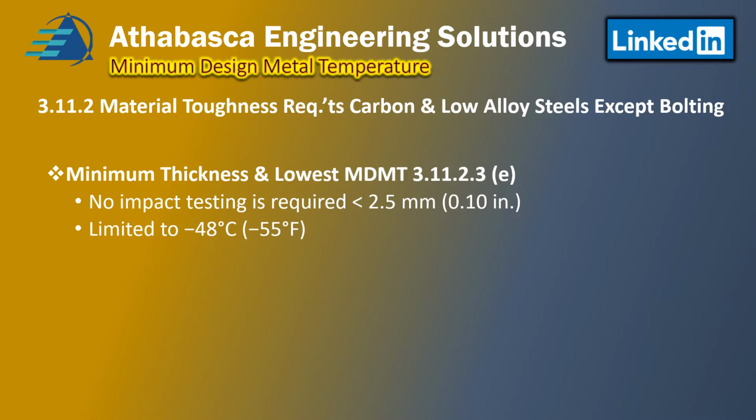The second one is you're limited to an MDMT of minus 48 or minus 55 degrees Fahrenheit. And this is identical to Section 8 Division 1 UCS 66D. It's just worded a little bit differently, but it's the same.